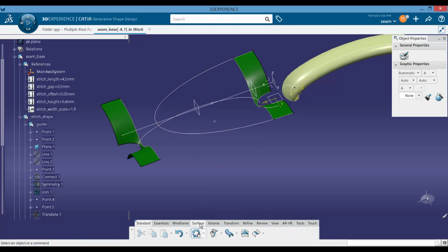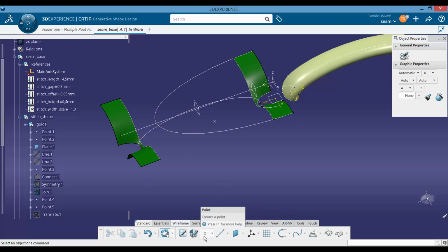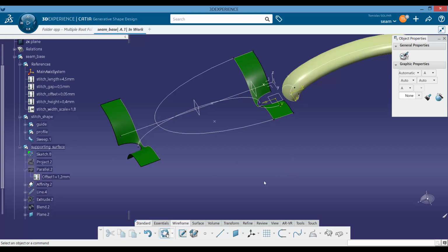The principle is quite straightforward. We need two lines that will blend. In order to do that, we will use this curve, which will split with this curve here, and we will keep this element here. How do we do it? So that we can keep it in a correlation that is always found and won't cause update problems, we will do it with split and keep options instead of just splitting it generally and leaving it undefined.